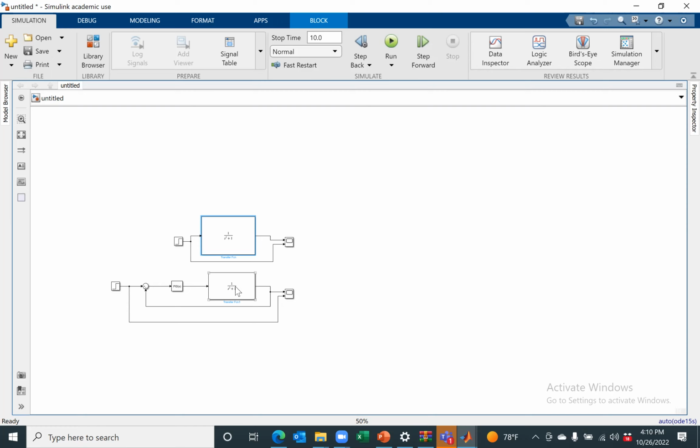So you go very close to the set point or where your friend is, and you add the integral term. So that integral term would add the controller effort that is cumulatively dependent on the oscillations near the set point, which means you will actually go close to the set point. Everyone understood this? That is the physics of PID control.